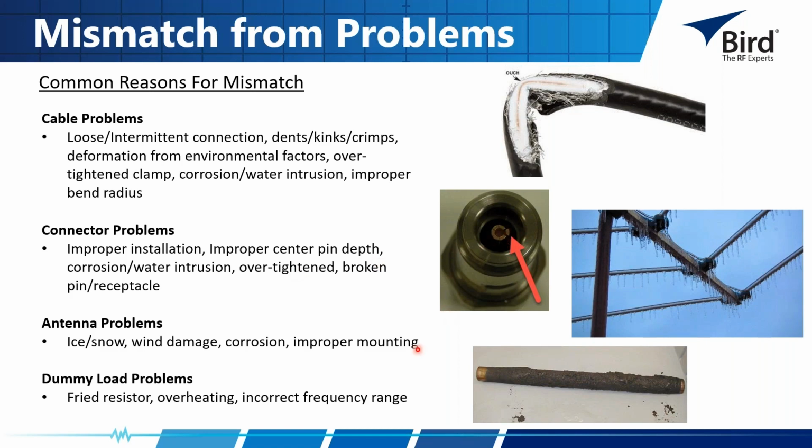When I'm thinking mismatch in terms of antennas, I'm thinking, like for here where we've got icicles hanging off the thing, antennas are a very reactive type of structure. Anything that you're going to put around them or on them or near them can result in some weird effects. I see guys out there, especially on the broadcast side of things, that might be having these VSWR monitoring systems in place because they want to be able to detect when something with the antenna has changed, because maybe they live in a colder climate and there's icing or something with snow that has now happened.